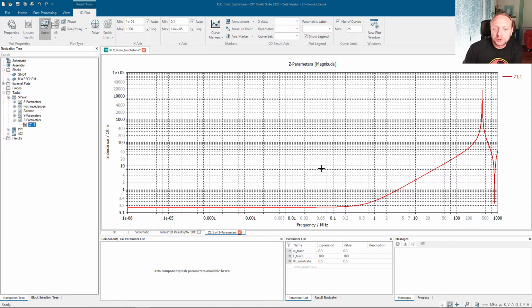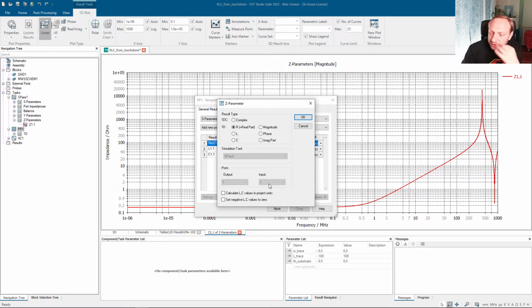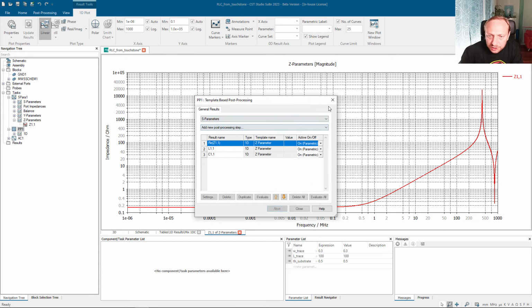And if I have the loop now, I can easily calculate the inductance and the resistance of the loop. You can now look up formulas. You have to divide over 1 over omega or whatever. Don't mind. Take a post-processing template and just calculate resistance for Z11. And it's important that I made this reduction from the two-port network to one-port network by shorting the second side.